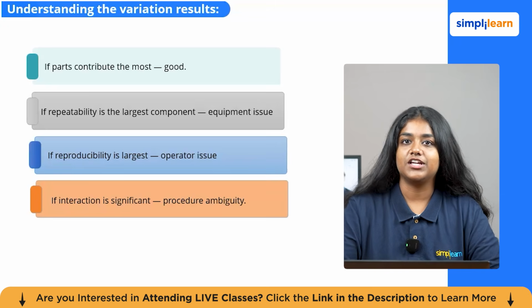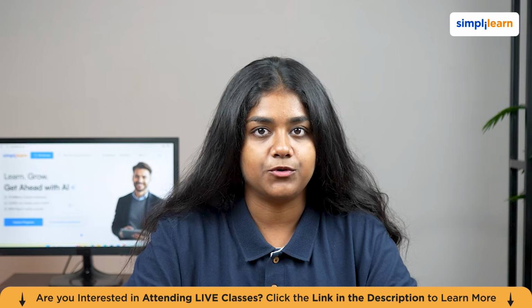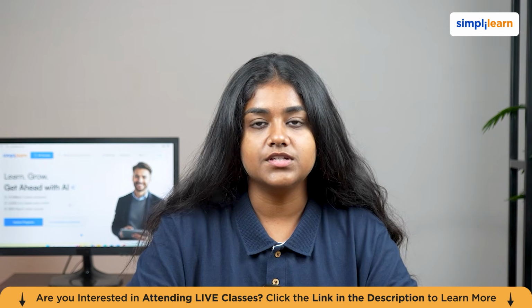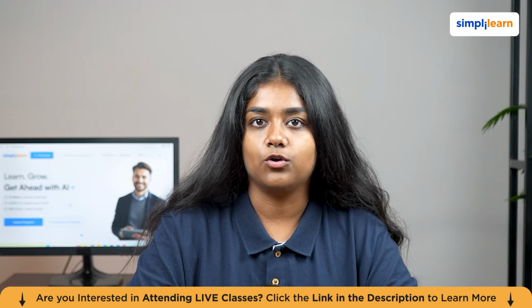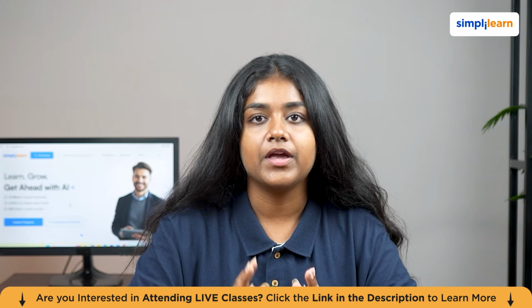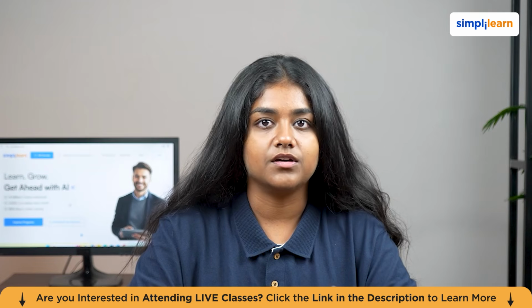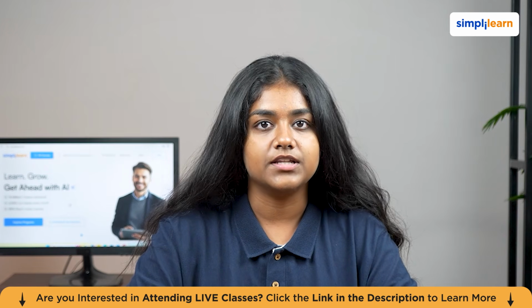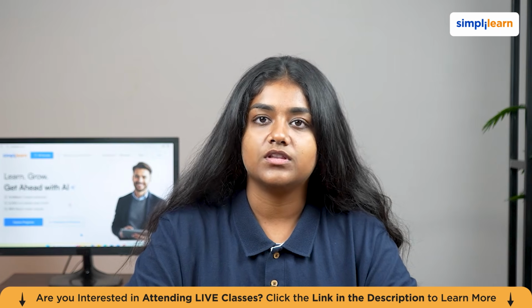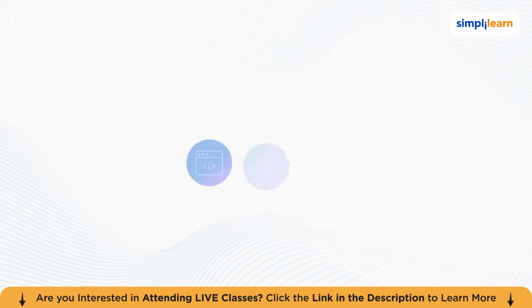So with that, we've come to the end of this module. In this module, we covered the most statistically rigorous ANOVA approach to Gage R&R analysis, which goes beyond the average and range method by detecting and quantifying operator by part interaction effects. We explored how ANOVA partitions total variation into parts, operators, interaction, and pure measurement error, and how the resulting variance components guide targeted improvement, whether the issue lies with the equipment, the operators, or an ambiguous measurement procedure.